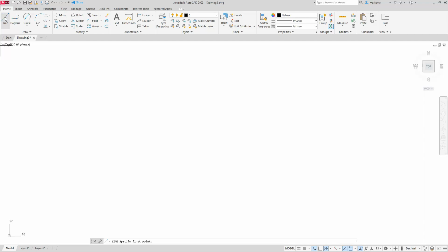I start off with the line, and like I said, I'm going to start in that location that I told you to. I'm going to start to the right of those decimals, and as I always say, my brain works in a counterclockwise rotation. So I'm going to click the first point, and now that line goes down at 15 degrees. I'm looking at my cursor here, and I'm just going to go down. Remember, I have this set to click at every 15 degrees. Once it's going down in this direction, make sure you're getting the green tracking lines. I'm going to type in 8, enter. And now I've completed my first line.